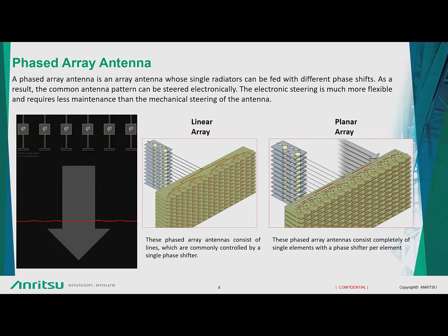But still there are so many antennas and so many components that you ought to test each and every component very wisely, because what can happen in these circumstances is that even if one of your components, or one of the phase shifters, or one of the antennas is not working properly, then the beam steering will go for a toss, and then the whole system can become inconsistent.